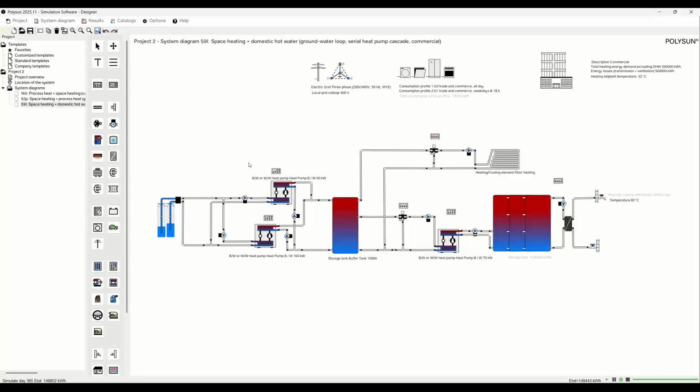So of course, when you have these systems set up with multiple heat pumps, then you can save a lot of costs, because the heat pumps themselves run efficiently. They are in themselves less expensive to set up than just one big heat pump, which needs to be specially constructed for the case. But of course, you also need to set it up correctly. And when you set it up correctly, you can save up to 40% of the costs compared to just installing an oversized heat pump that runs inefficiently and breaks early due to wear and tear.